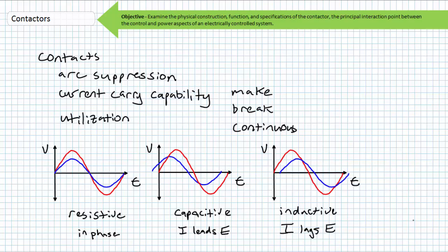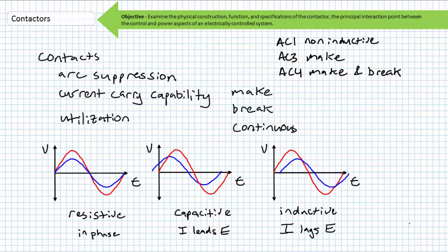Plugging is the intentional disconnection and sudden reversal of a motor spinning in a particular direction in an effort to bring it to a quick halt. You better believe such an event is associated with an extreme current draw. Motors that are jogged or plugged often will experience excessive contact wear, and contactors designated for this purpose must be used for this application. The IEC divides contactors into utilization categories. For example, a contactor with an AC1 utilization is designed to make or break connection for only slightly inductive loads, such as resistive heating elements.